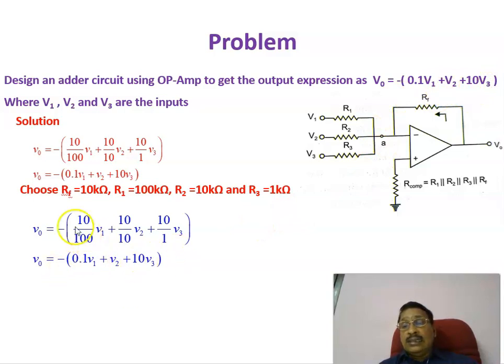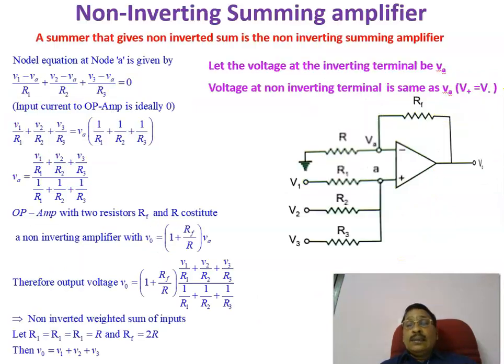That is the way you can implement this voltage equation, with an inversion. That is why it is called an inverting summing amplifier.